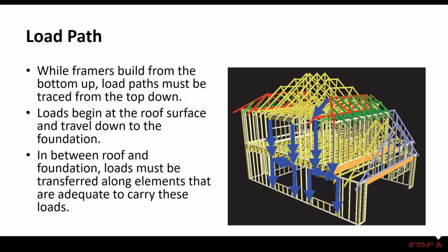Ideally, you'd like to have the correct framing members in place so that as the load accumulates going through the structure, the members that are helping to transfer that load down through the foundation into the ground are sized correctly, both from a strength standpoint and a serviceability standpoint. Obviously, when someone is building, they're building the structure from the ground up, but the structure is being designed and the loads are accumulating really from the top down.